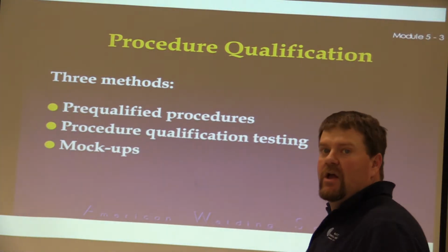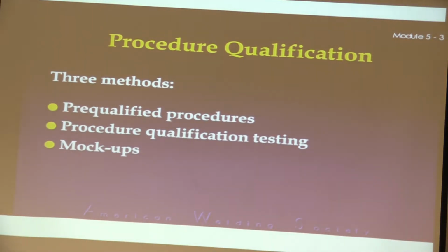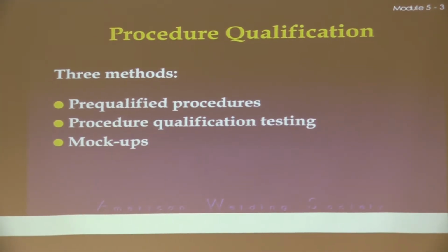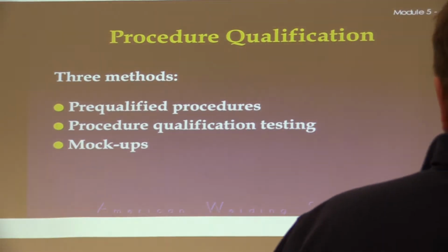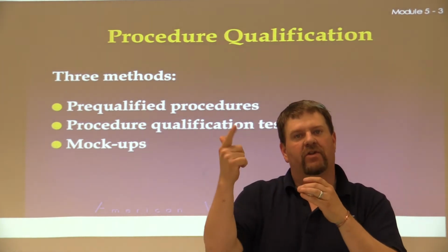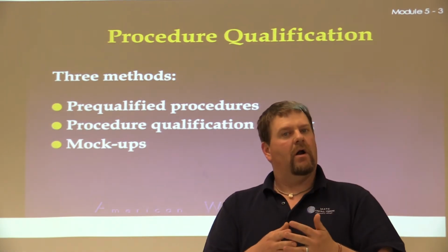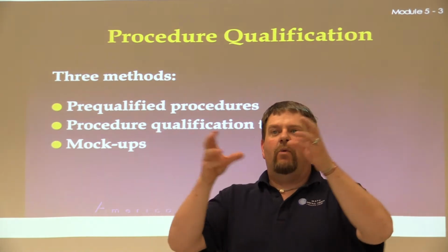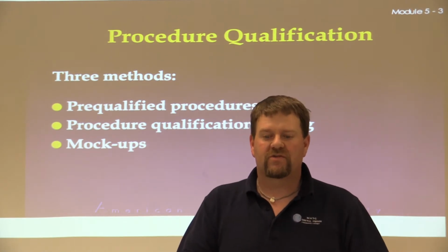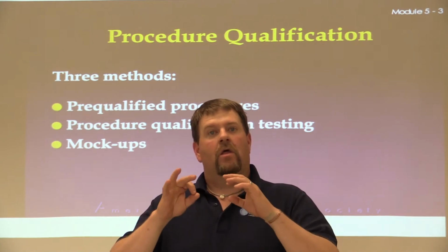It's quite simply this. The procedure shows that the mechanical abilities of this equipment is fine. So if I join 7018 and A36 steel, it matches the mechanical properties, the tensile, the yield, the elongation, the ductility, everything falls within that spec. That's the PQR, right? So we welded it, now we've tested it, and all of our test coupons, our tensiles, our nick breaks, our reduced section tensiles, have all fallen within the spec that we need. So that means that yes, it's proven, everything is there.